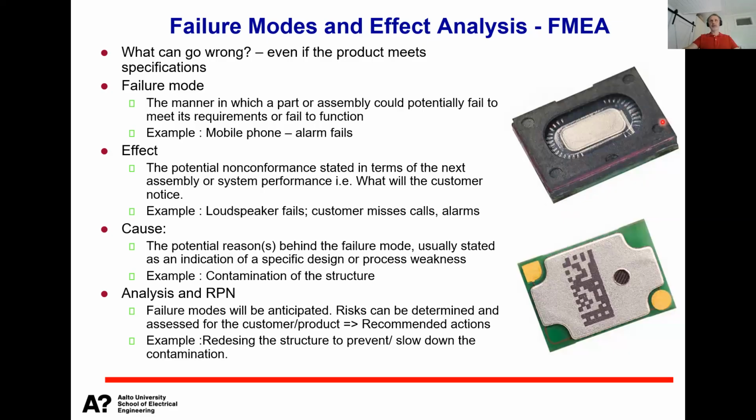So here is just a picture of this kind of miniaturized loudspeaker, which could be in your phone. Both microphone and loudspeaker have as their physical basis a moving membrane which moves the air. So it means that this kind of component cannot be completely sealed. It cannot be hermetic in that sense. You need to allow the external air to move in and out of the component in order to get the sound waves in and out. In the loudspeaker case, of course, out; in the microphone case, in.